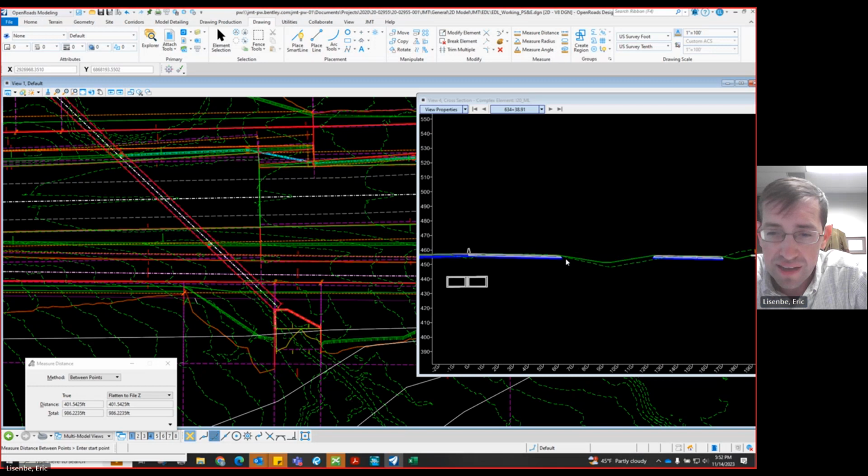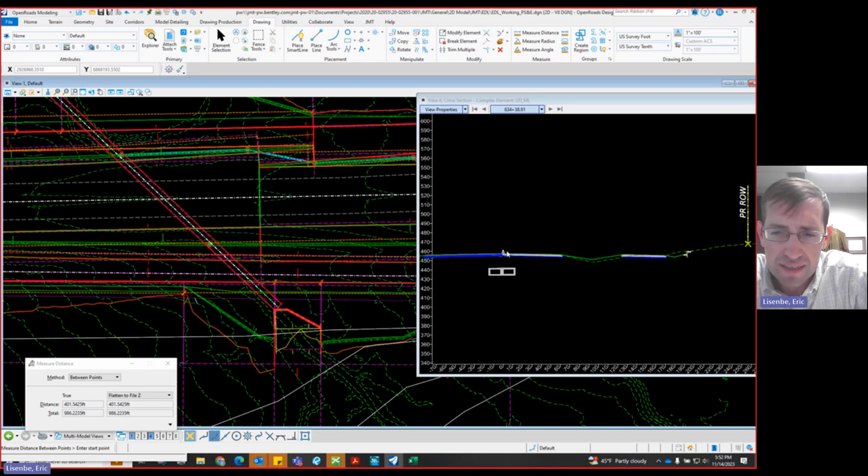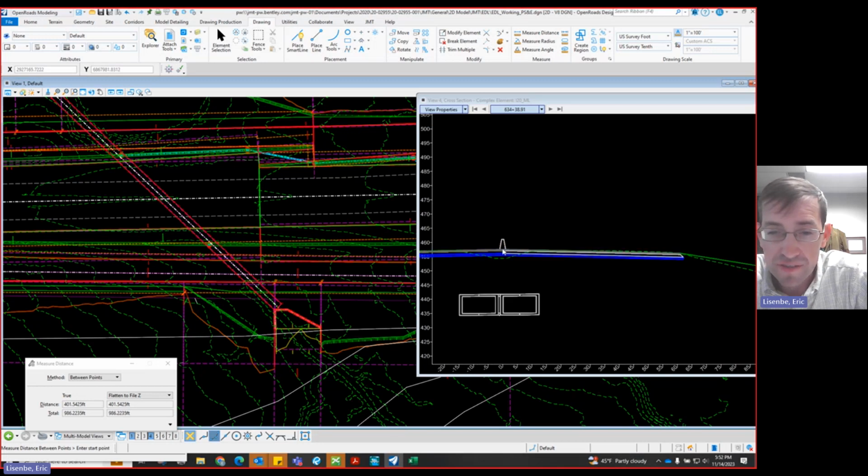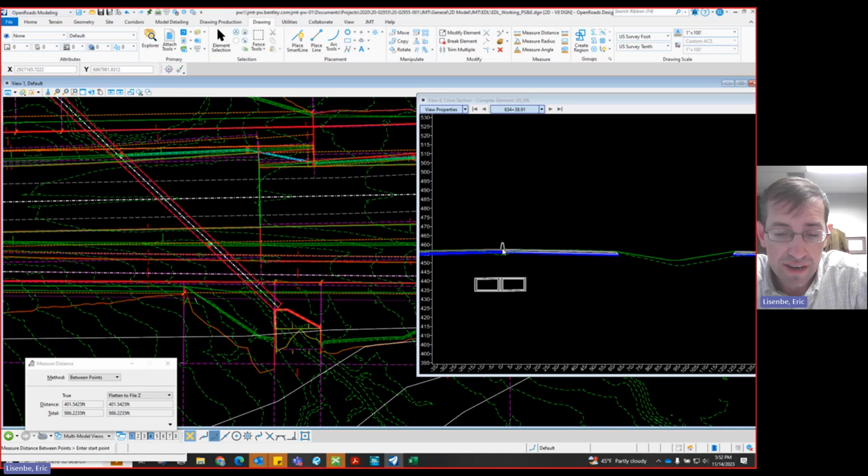And then, so I'm going to enter that in. And then I like to, just in case it overtops, I think on the downstream profile on the deck editor, I think I will just use this PGL of the main lanes is my plan right now.